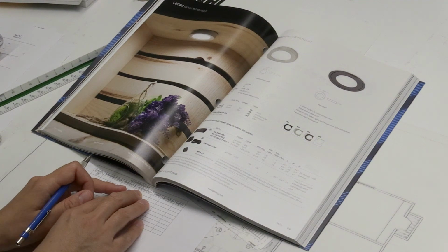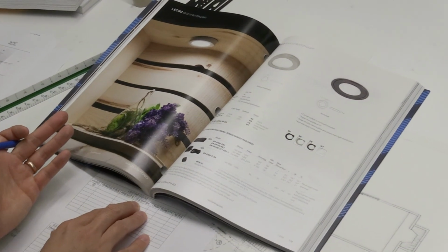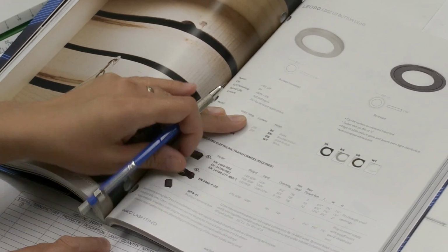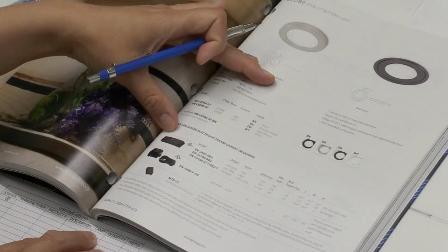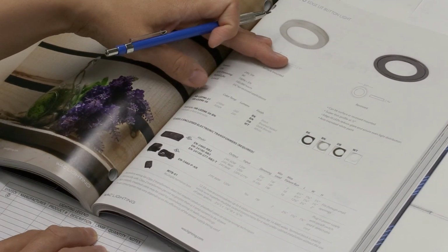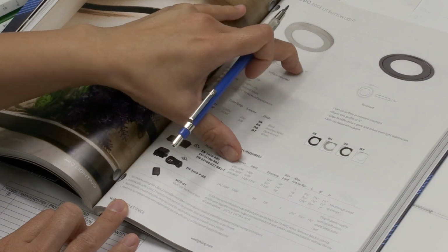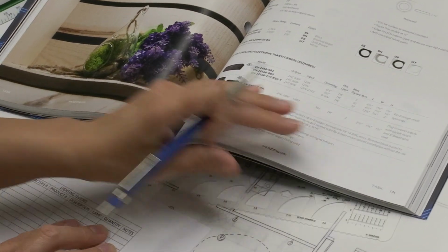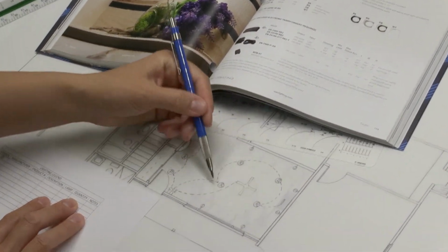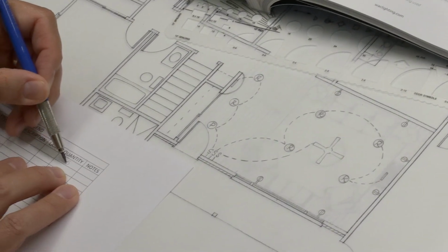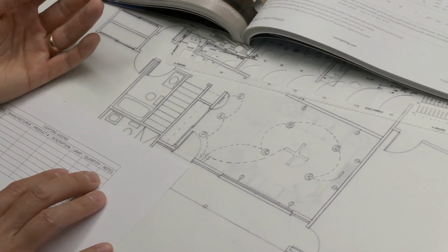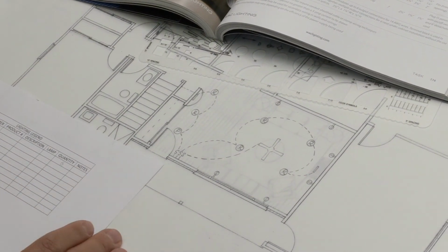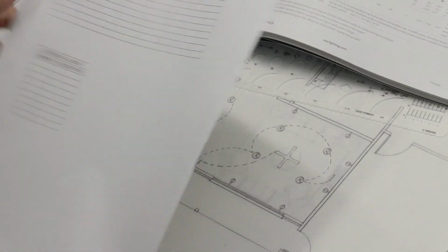And then the description, what is it, surface mounted lighting or recessed. And then you have the lamp, that means how many watts it is. And you'll have to find it here, the wattage, here's the model, and then 60 watts. And then how many of those you need. Let's see how many we need here, 1, 2, 3, 4, 5, 6. So I put 6 here. And then the notes, you're just putting like in which room you are putting, where you are placing this lighting fixture. And this is it.